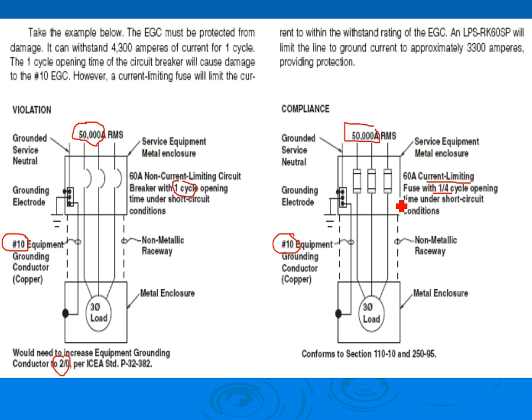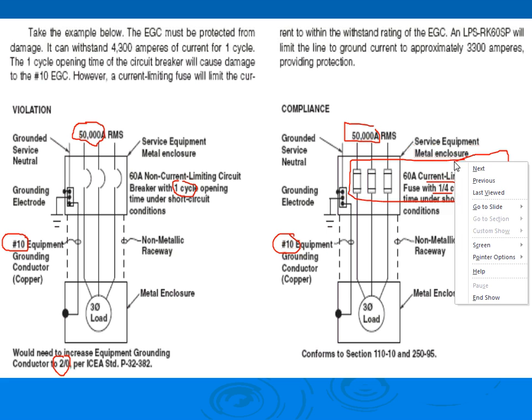The reason why you really need to use current limiting fuses here, and don't misunderstand me, I think they're a great application, is to have better protection for your controller, for your magnetic starter, VFD, soft start, and in the process you're also protecting the conductors, definitely, but not just to protect the equipment grounding conductor though. So any comments, any questions, guys? Any comments about that?